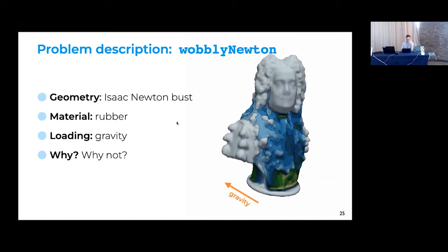So what is it? I just assume it's rubber, and I assume gravity is in this direction, and I fix the bottom. I start off with no gravity, then gravity kicks in. The whole thing is fixed at the bottom, and imagine we were holding it sideways. It just falls and bounces. The material is elastic, so that means it doesn't dissipate energy in the mathematically perfect sense. It should keep bouncing back to position 0, down, back to position 0, converting potential energy to elastic energy, storing it, and converting back. So that should run forever. With numerical methods, the discretization may diffuse energy so it disappears, or it may explode if it adds energy.